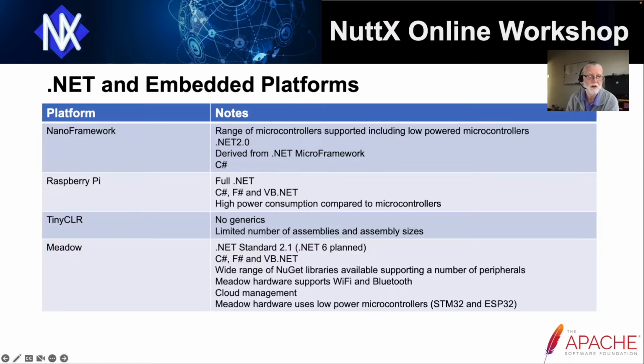And the Meadow board uses two microcontrollers, the STM32, which is our main controller running the .NET platform, and the ESP32 providing access to Bluetooth and Wi-Fi. So similar to Nano Framework and similar to Tiny CLR, we're available on low power platforms.